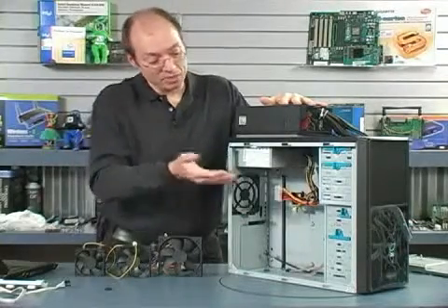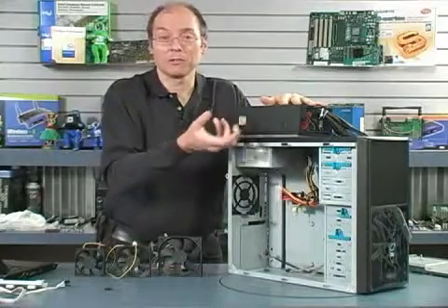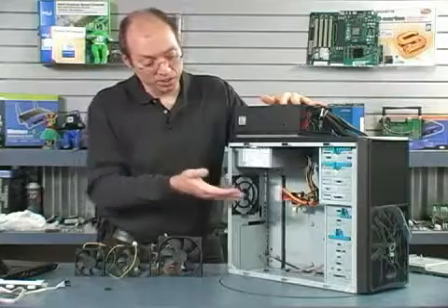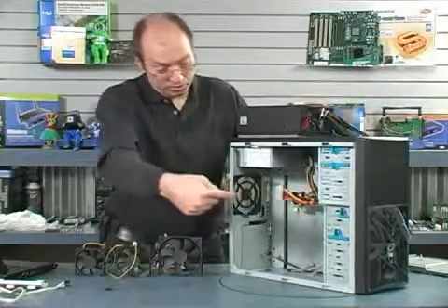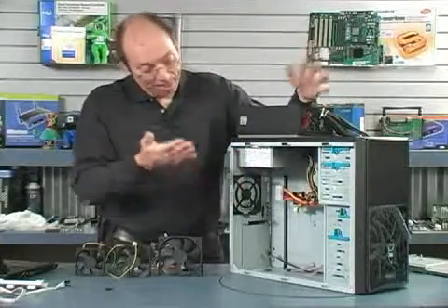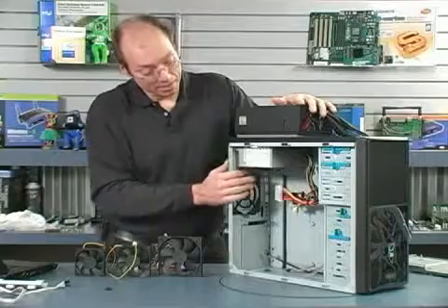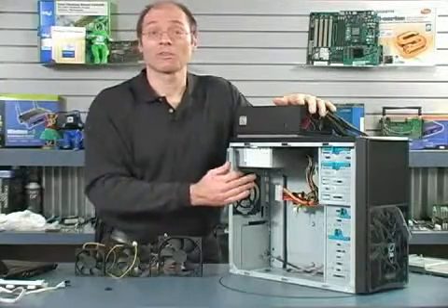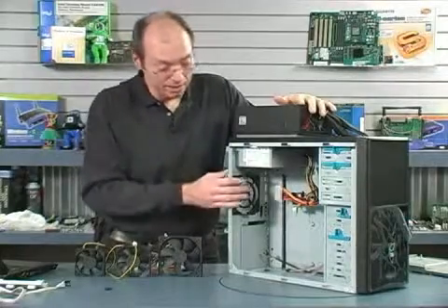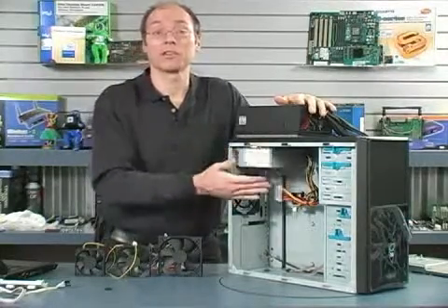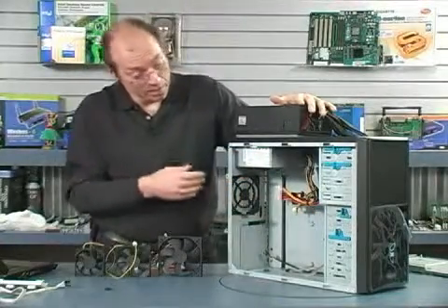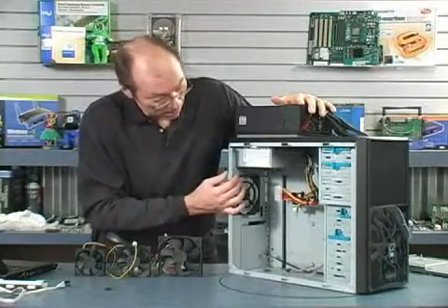Well, the problem is they don't really mount very securely. They allow the drive to move a little bit, and you end up getting rattles and noise. And without the secure mounting, without screws going in through the case on either side, you lose a bit of rigidity too. So anymore I take them out and discard them, and I mount all of the drives with screws. It does take a little bit more time, but I think you end up with a more securely mounted set of drives. The cooling is better because they're more directly attached to the metal of the case, and it just seems to work out better.